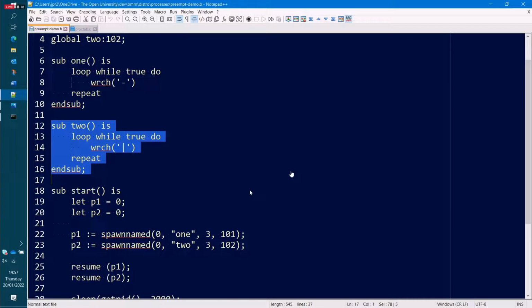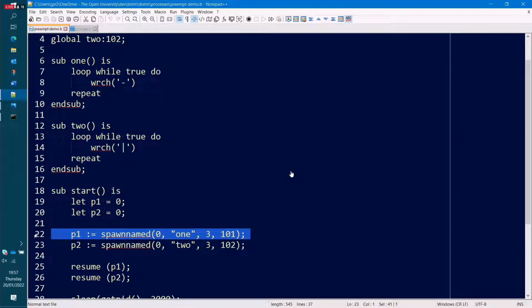Okay, well, I can show you that if we can go back to the screen for a minute. I think my demo here, I just very quickly showed you that on screen, that the 2 lines which create the processes are down here, and one of the parameters in there is 3. That's the priority at which those 2 processes are running at, so it's priority 3. So I allow small numbers to control the priority. Priority 0 is for the idle process, the lowest.